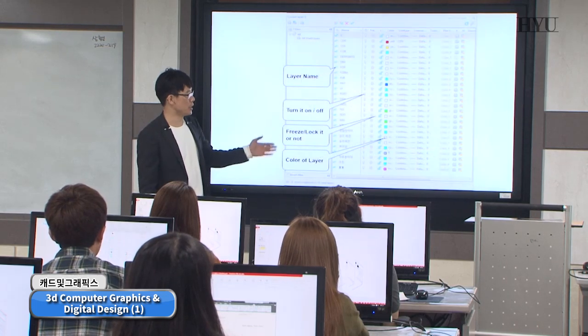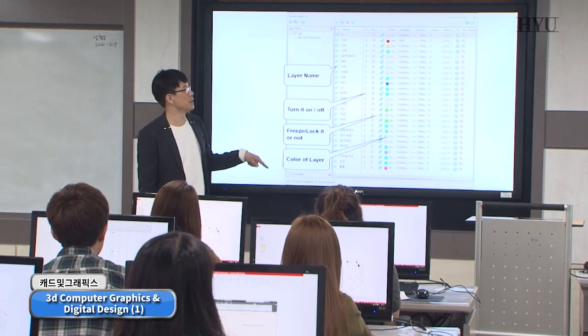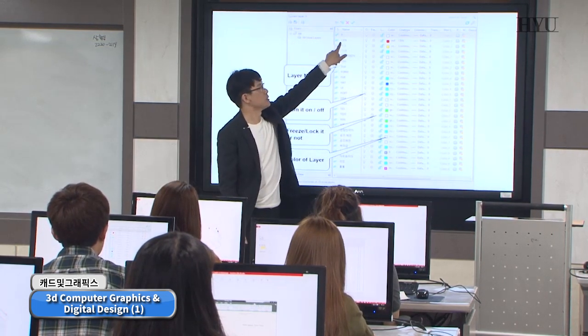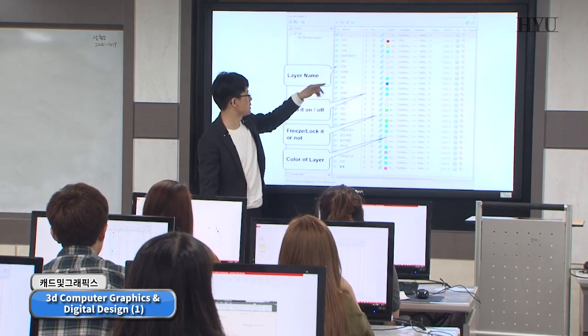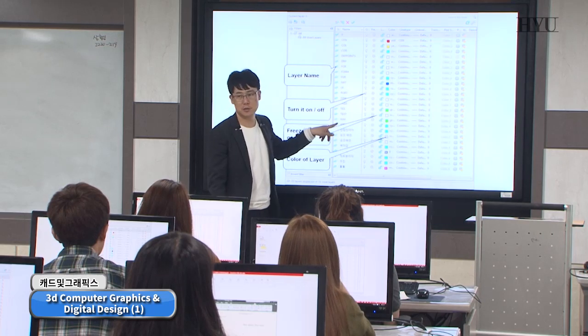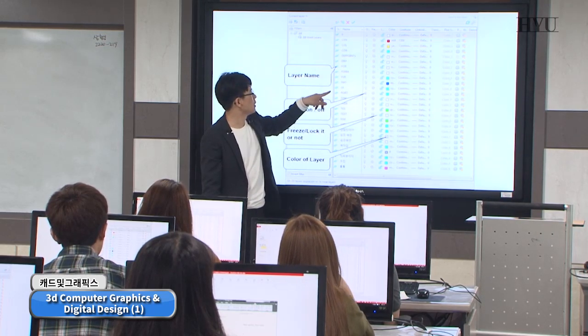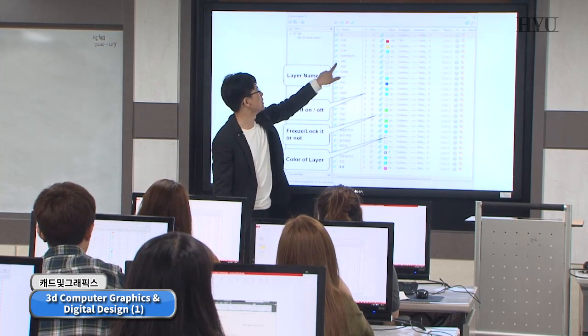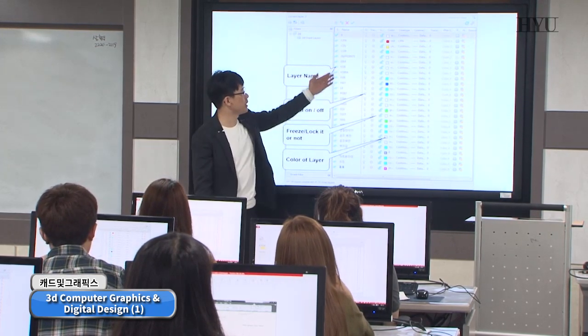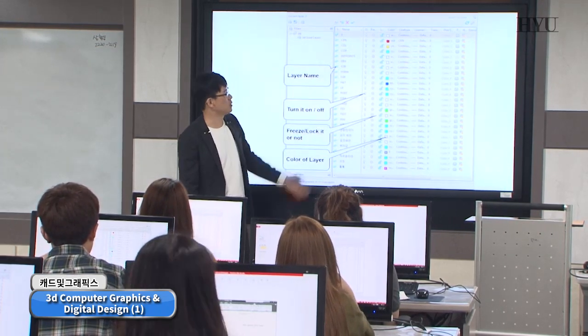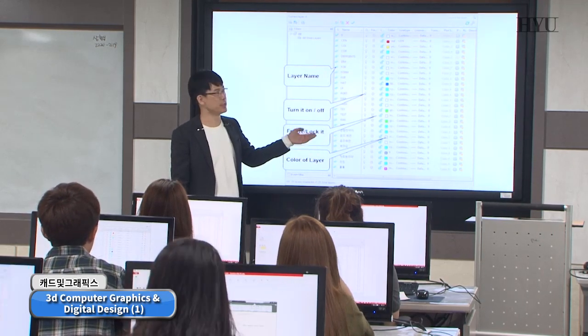Especially in AutoCAD, take a look. This is an AutoCAD layer. CN usually means center line, okay? Center line for walls. How about walls, okay? Text, furniture, dimension, corridor, columns, all of them can be assigned to this kind of layers with appropriate names.